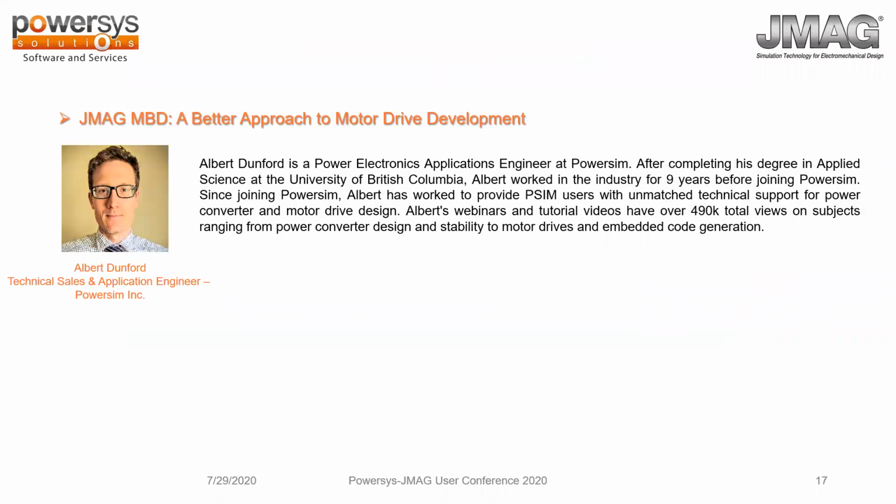The next topic I would like to introduce is this: we have seen how we can generate the RTT file, which is a high fidelity plant model, or a 1D lookup table, which incorporates pretty much all the motor data, including your saturation and slot harmonics, and now we are handing it over to control simulators and HIL system level simulation. First, I would like to hand it over to Albert from PowerSim.